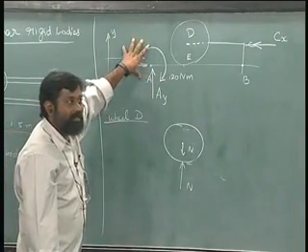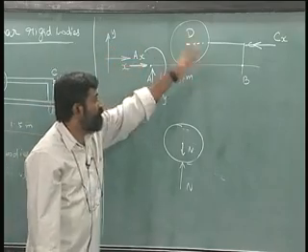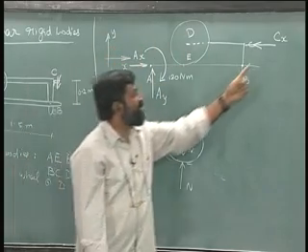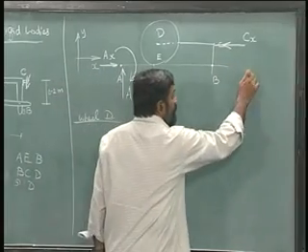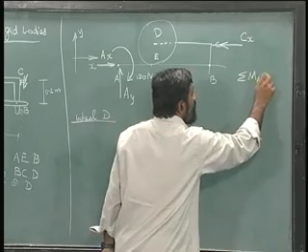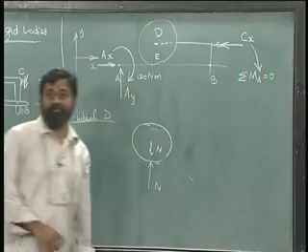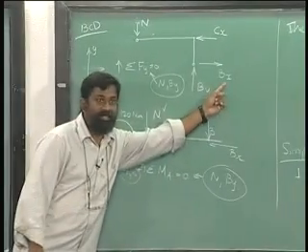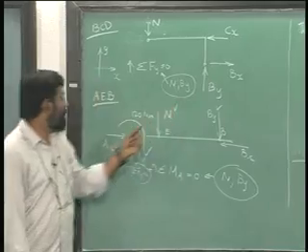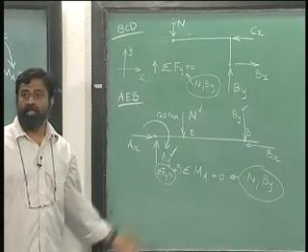Remember, this system of planar bodies, free body, will help me solve for Cx directly. This is an important point you have to note. If I do sigma Ma equals 0 here, I will get this directly. Having gotten this directly, I can find out Bx. Having found out Bx, I can find out Ax, which means I have solved for all the unknowns in this